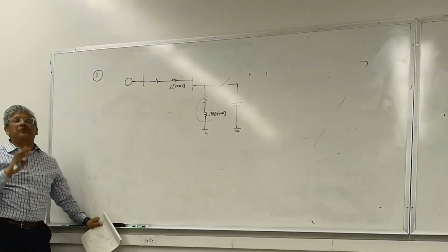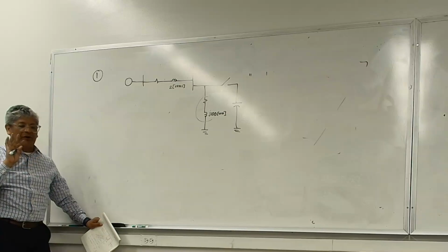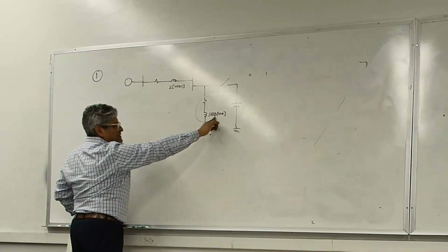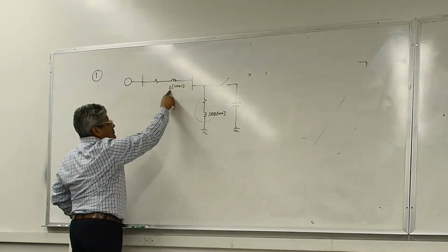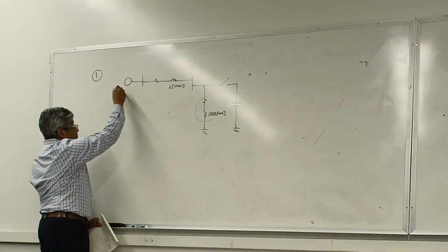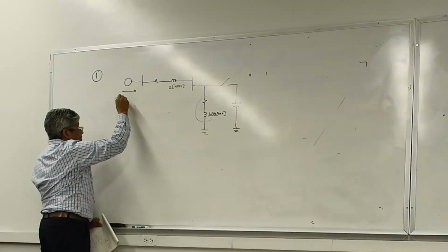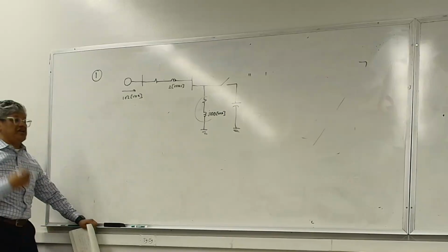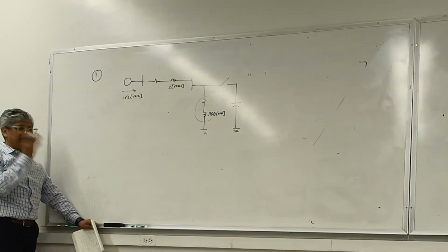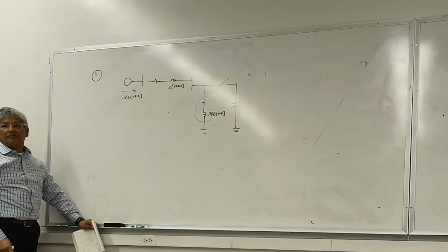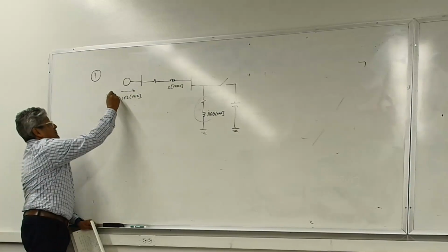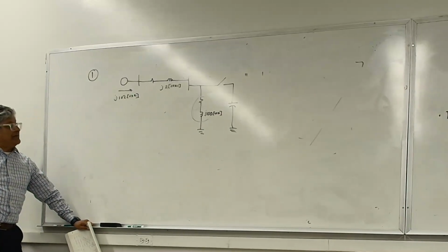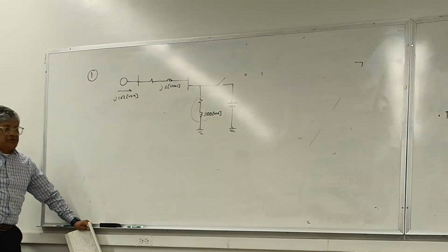Again, I'm just talking about imaginary power. Forget about the real power for a second. If I have a sink of vars of 100 and a sink of vars of 2, how many vars have to come from the source? 102 vars, coming from the utility or the generator or the solar PV plant, whatever is producing the energy for you. That would be j2, right? J and J, thank you, yes. All right, that's great. So 102.